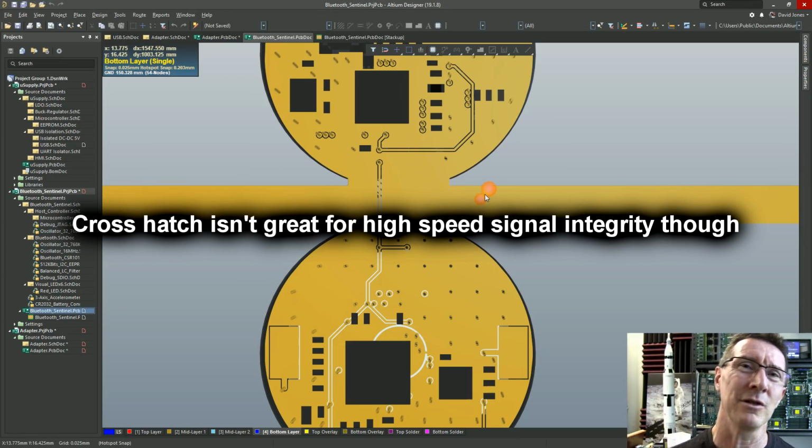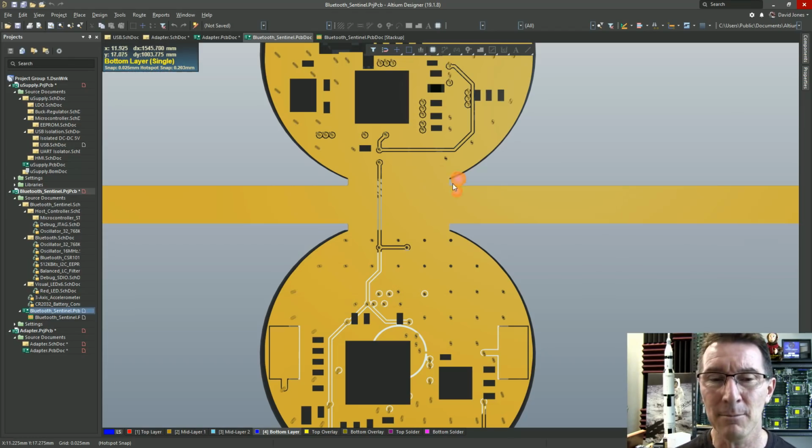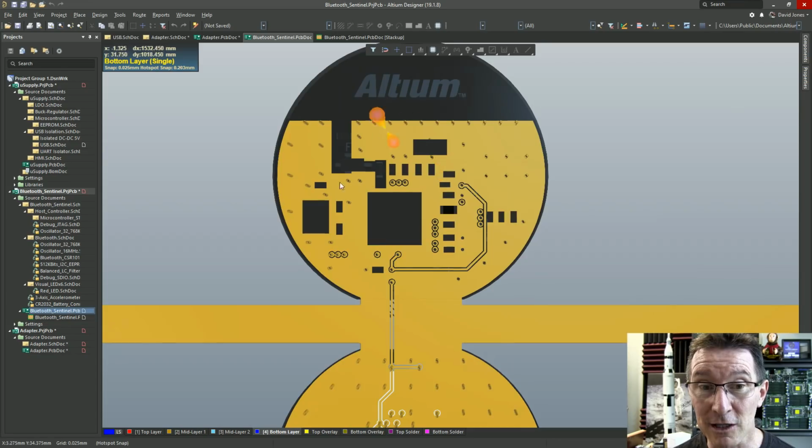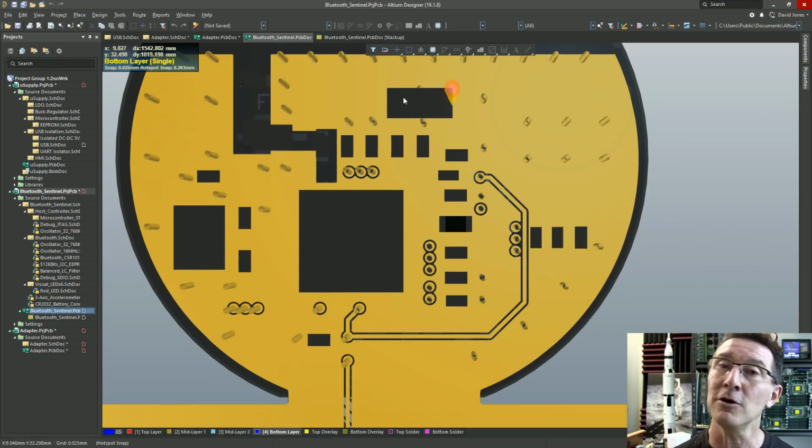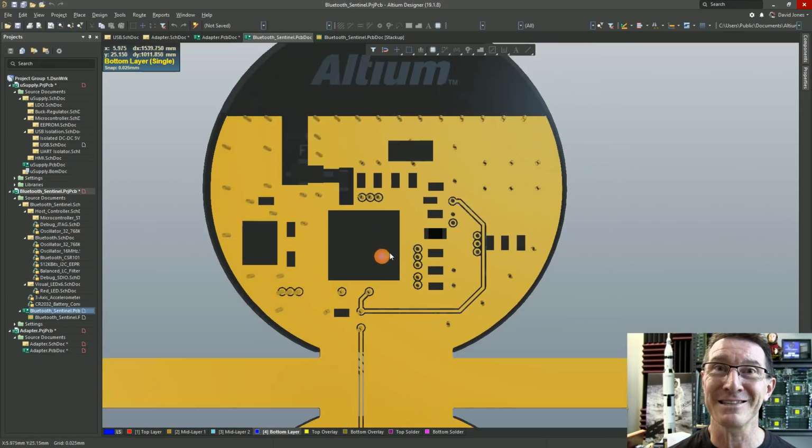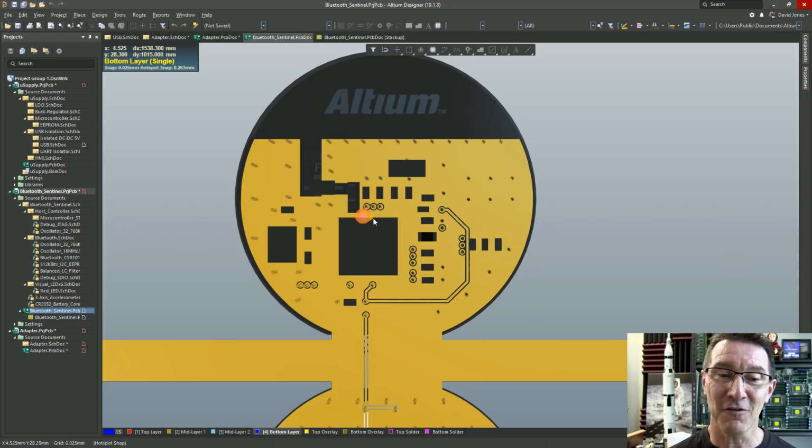Unless you absolutely need a solid ground plane, you would do flexes as a crosshatch. But when it goes inside the board like this, you can certainly make it solid because it ain't flexing when it's sandwiched inside that fiberglass.